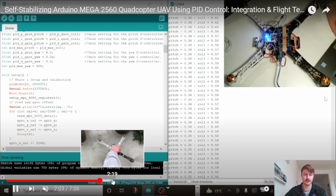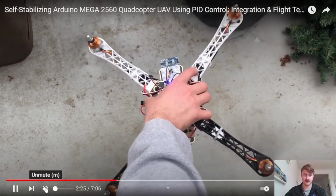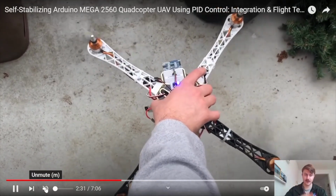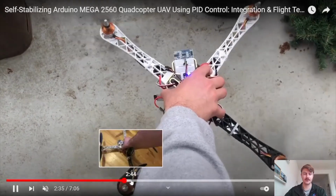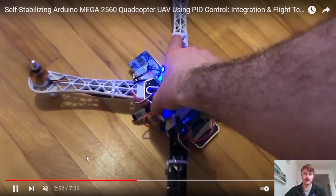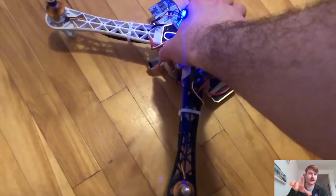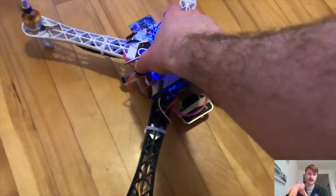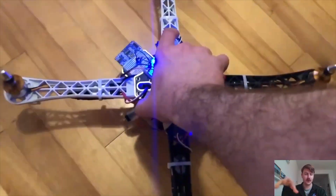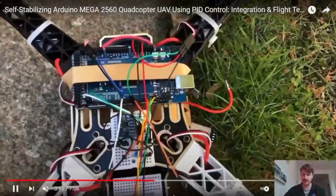Again, jumping ahead here. This is me testing the system with just the P gain and seeing that the motors were adjusting and trying to compensate for the change in body position as expected before I did more PID tuning. This is after I had tuned the PID controllers, and I was not actually holding it, I was just acting as a guard next to it, in case it started to do a corrective action very fast, so I could maintain control of it, but that was all pretty much its own control.